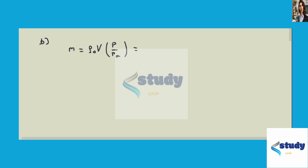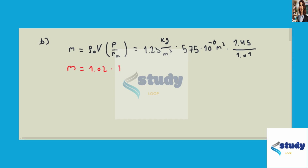So this will be equal to 1.23 kilograms per meter cubed times 575 times 10 to the minus 6 meters cubed, and then times the ratio of the pressures, which is 1.45 over 1.01. This is an approximation for the atmospheric pressure, and when we evaluate this using a calculator, we obtain that mass equals 1.02 times 10 to the minus third kilograms.